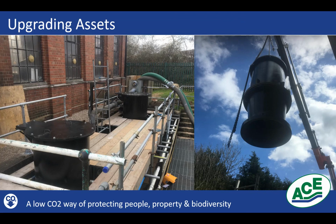So the pump will adjust its speed depending on the level difference, both upstream and downstream. So it's constantly measuring the intake depth and the outfall level and choosing the speed that is most efficient. In this case, they're trying to actually also keep a constant flow, which helps from a fish-friendly perspective, which is very important, but it also helps enormously towards producing a truly efficient pumping station.